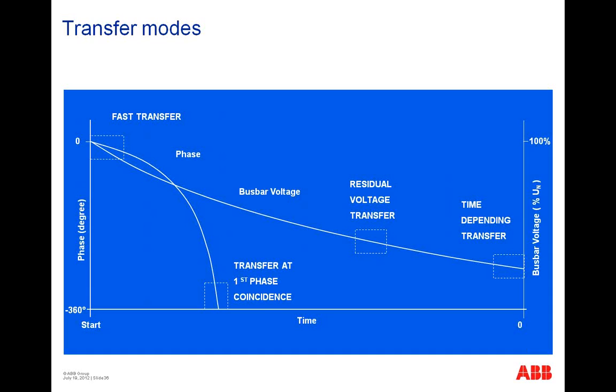That's not possible. You cannot start all the connected motors at the same time. Then we send also load shedding signalization that only a few motors are still connected or nothing. But after this 2 or 3 seconds time-dependent transfer, the breaker will close and you can manually start all the loads once more again. Okay, for sure.